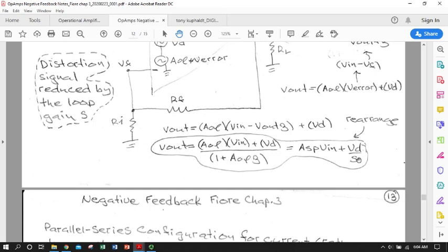So kind of to give a recap of the series parallel, when we bolt on a series parallel negative feedback network onto our bare naked op amp, and if that feedback network has a feedback fraction of beta, we can write an expression for loop gain or sacrifice factor in terms of open loop gain of the op amp and beta, which approximates to 1 over beta.